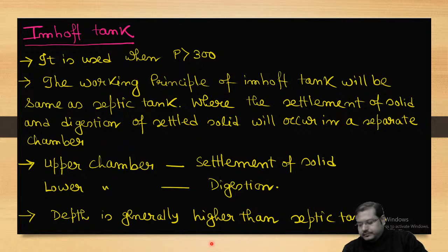Now, just to know about certain points of the Imhoff tank. It is used when the population is more than 300. The working principle of the Imhoff tank is the same as the septic tank. That means settlement of solids and digestion of settled solids will happen.